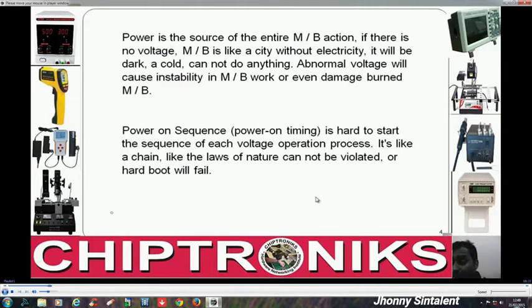How does this soft start work? What are the various signals in the soft start? We are going to unearth those things also, and I think very few have actually mastered those things, how to correlate with BIOS and how to read the data communication during the SM bus communication or in the LPC communication. For that we do require some specific kind of equipment called a logic analyzer, and I'll also show this in today's class, when we are going to sniff out the data from the SM bus communication. Okay, so let's go to the next slide.